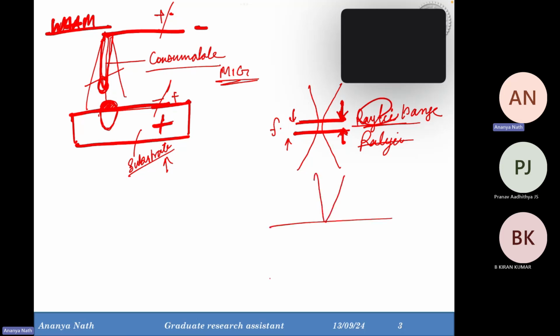But in case of DED, if we are melting the material, we never do it in focus. The laser will be like this, and here the deposition takes place. Because we don't need very high penetration depth inside the substrate. Why? We want the material to be deposited over the substrate, and we want the fusion between the first layer and the substrate. This is true.